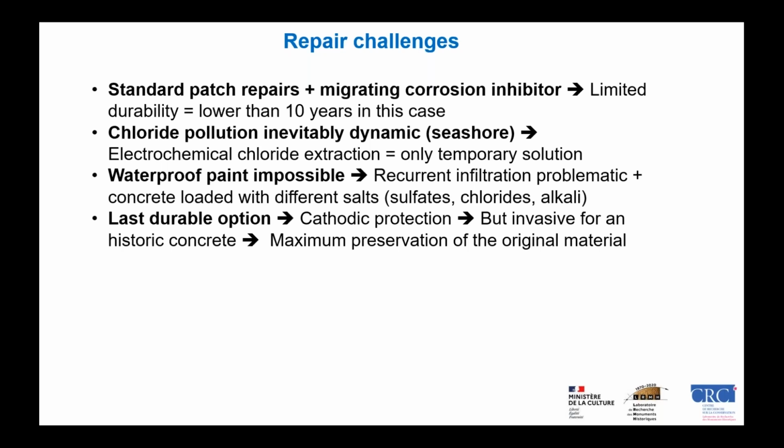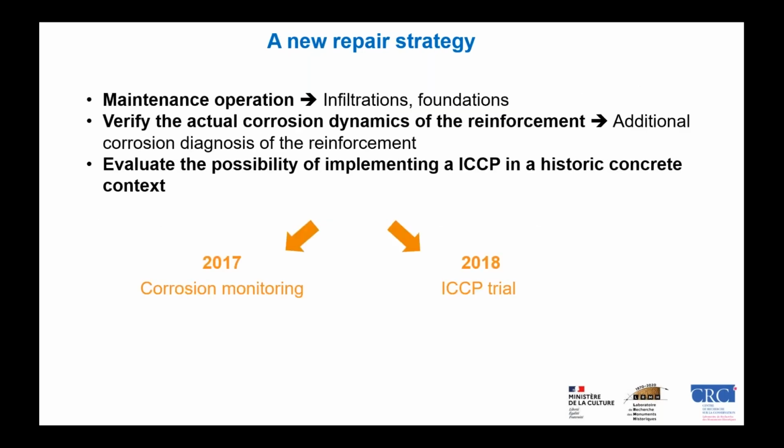Waterproofing paint was impossible because we had recurrent infiltration problems, and the concrete was loaded with different salts. So the last durable option was cathodic protection, but it's quite invasive for a historic concrete, where we expect a maximum preservation of the original material.